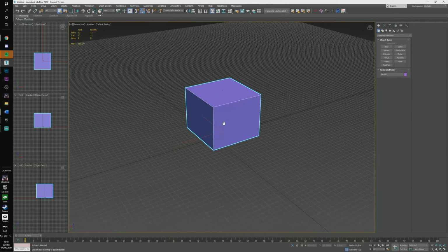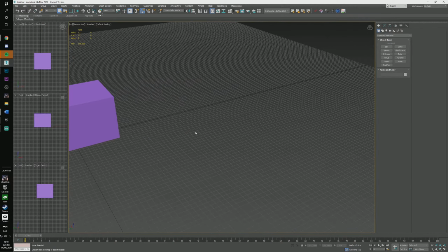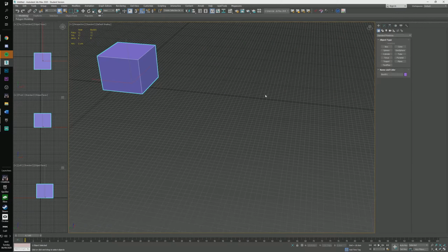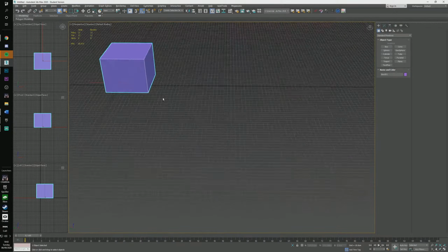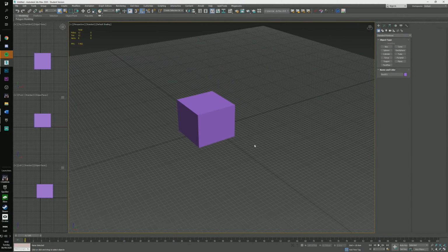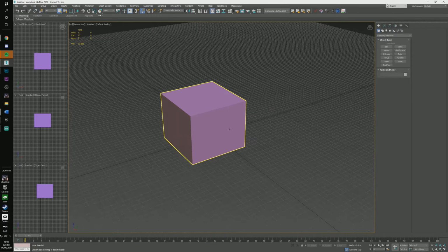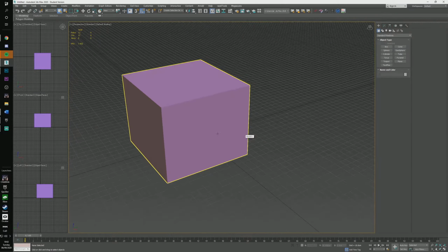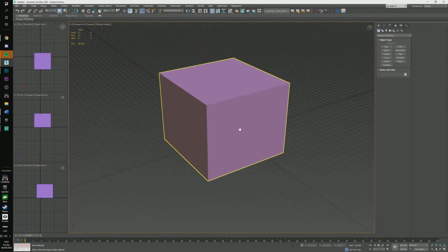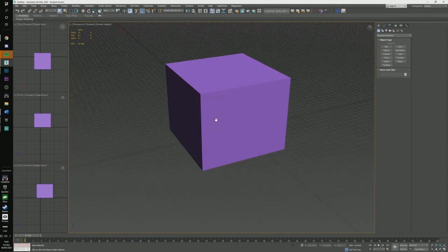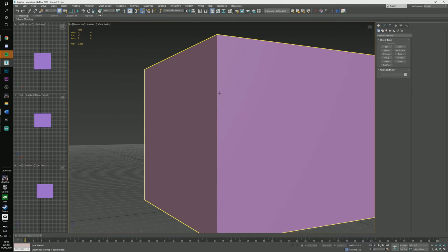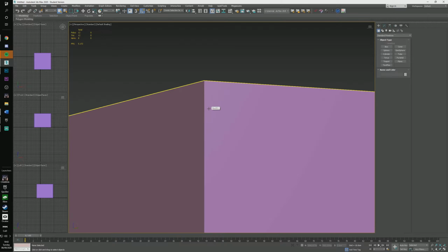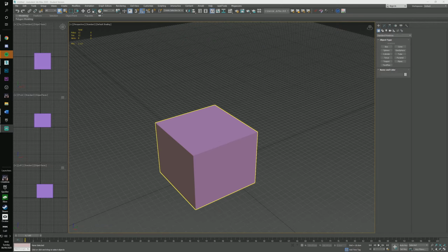And this orbit is based off the thing that you do have selected. So if you don't have something selected, it'll just orbit from around there. But now if I start doing that, it'll orbit from around that. Okay, so with orbit and panning, now we want to be able to move forward and backwards, and you can just do that with the zoom as well. So middle mouse with Alt to orbit, and then you can usually get wherever you need to be fairly easily.